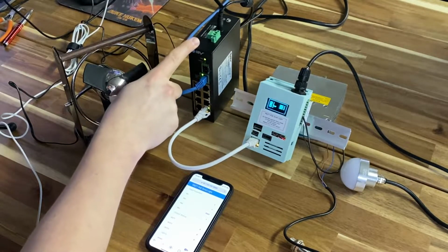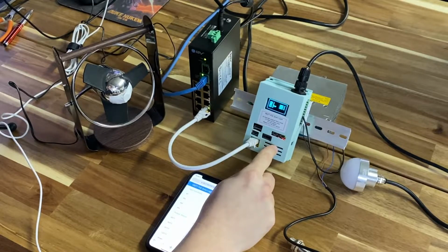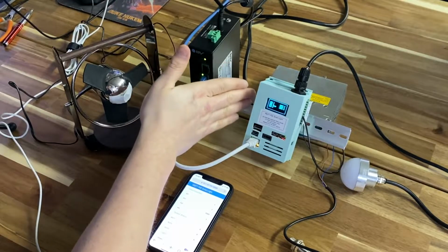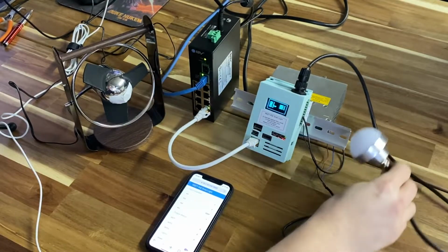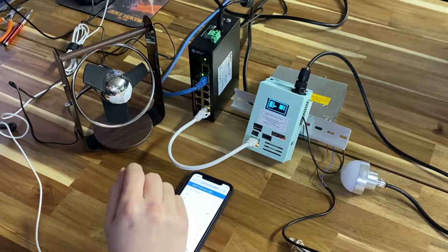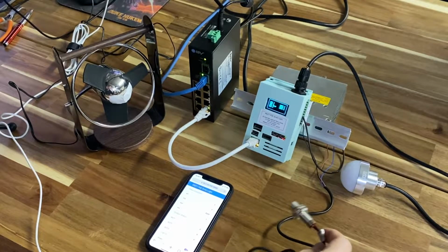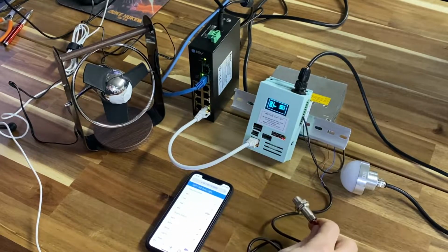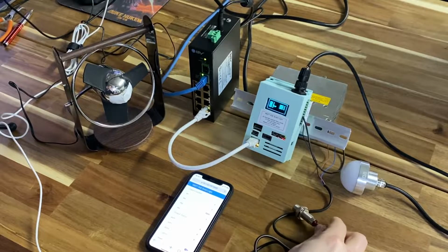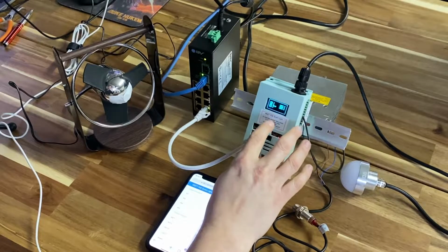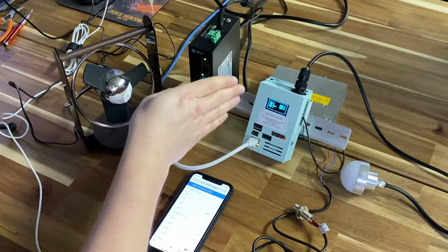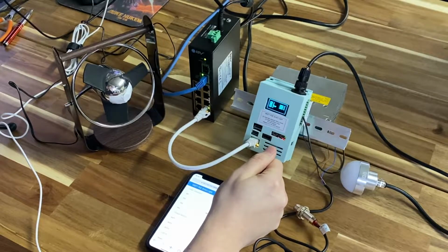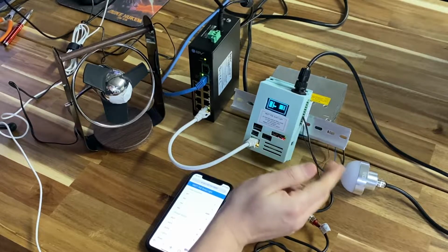So this PoE switch here is providing 48 volt power, which is then internally dropped down to 24 volts to power the inputs and also to power the light. Also, we have just a simple prox switch connected into it so we can demonstrate how that is working later. The screen is displaying right now the count of the number of rising edges on the inputs, and then on the right side we're going to show the status of the lights.